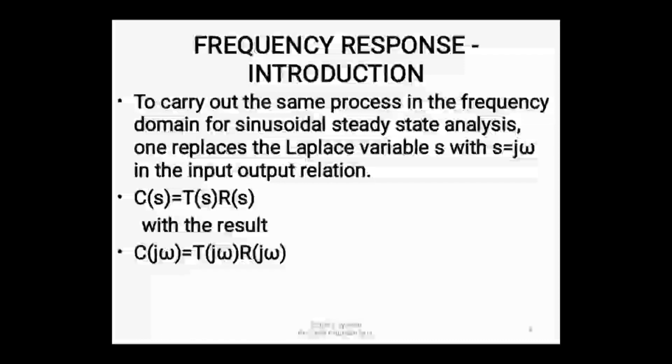To carry out the same process in the frequency domain for sinusoidal steady state analysis, one can replace the Laplace variable s with s is equal to j omega in the output and input relations. So, as we can write, C(s) is equal to T(s) into R(s), which results in C(j omega) is equal to T(j omega) into R(j omega).